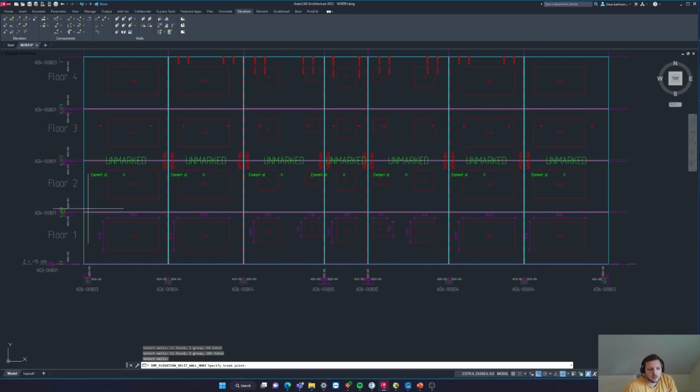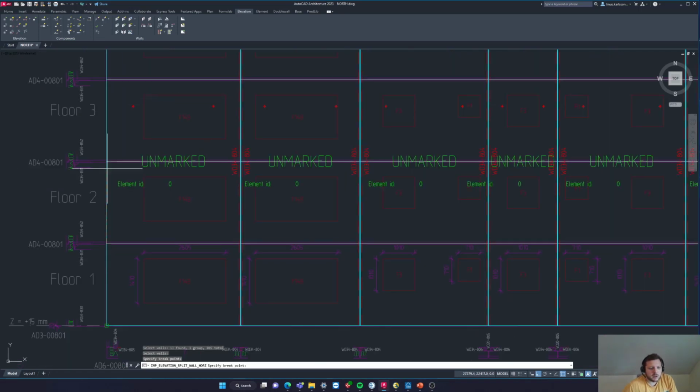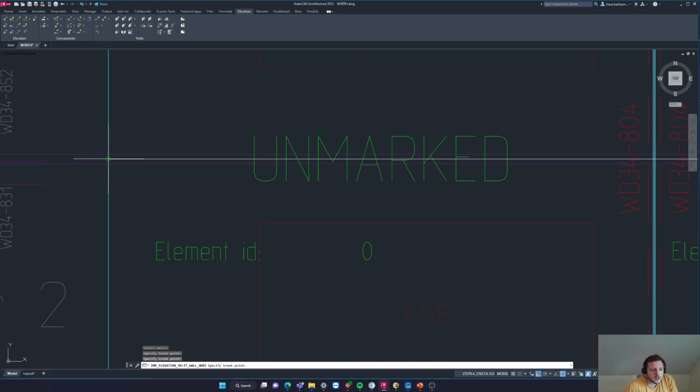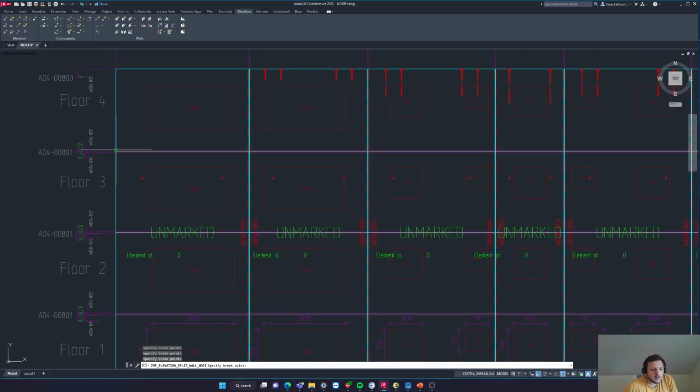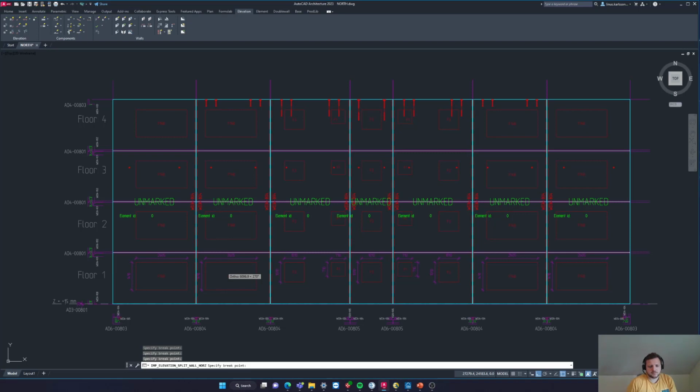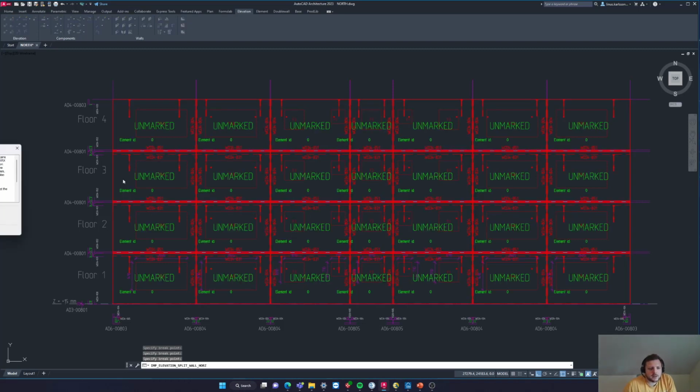Just click OK, and do as I did before here. Do some clicks here. So what it does now is redraw all elements, recalculate the mass, and place the lifters and the bracings, and also apply the end caps like this. So now in just a few minutes, I went from having a whole facade to having the proper elements that I want to have.